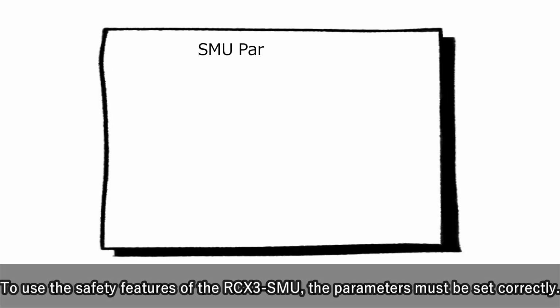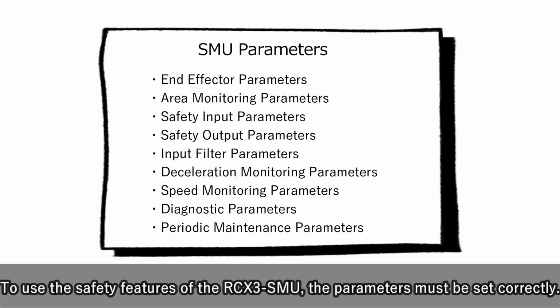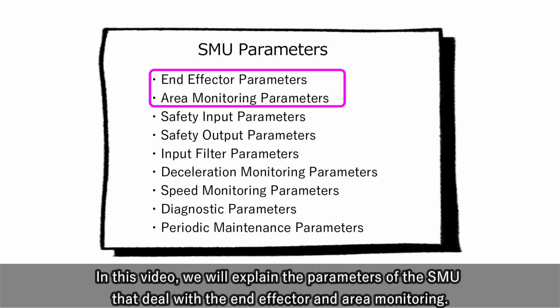To use the safety features of the RCX3-SMU, the parameters must be set correctly. In this video, we will explain the parameters of the SMU that deal with the end effector and area monitoring.